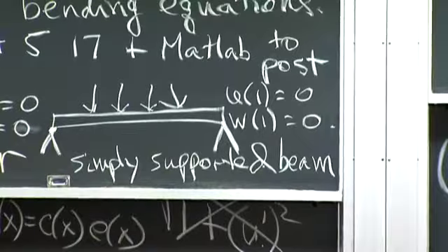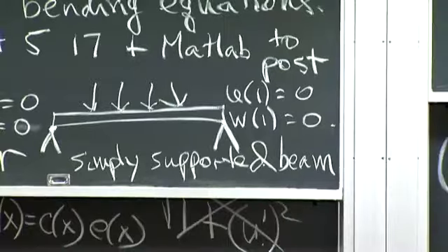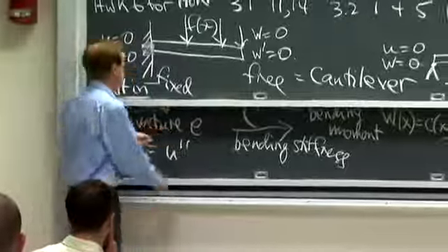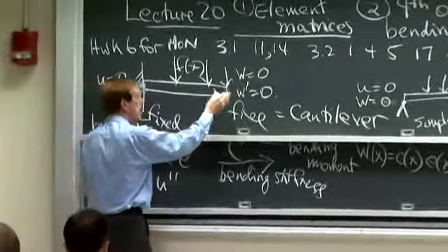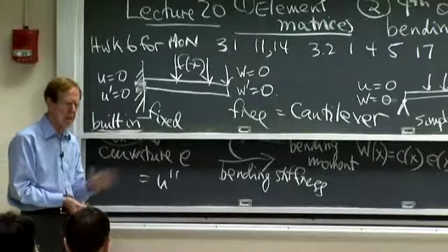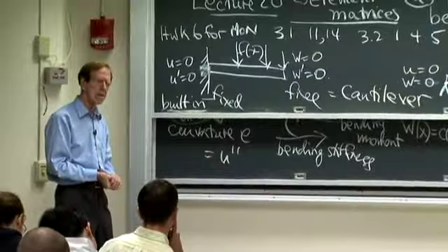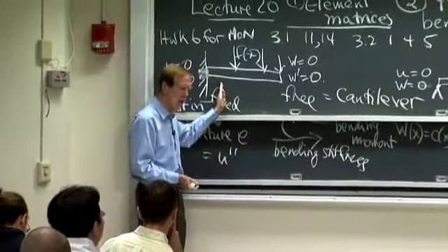That would be the boundary conditions, 4 of them, for a fourth order equation that we'll just write down in a minute for simply supported. And we could have a mix. It could be simply supported here, free here, I think, or maybe that's too risky. Would that be a singular case?